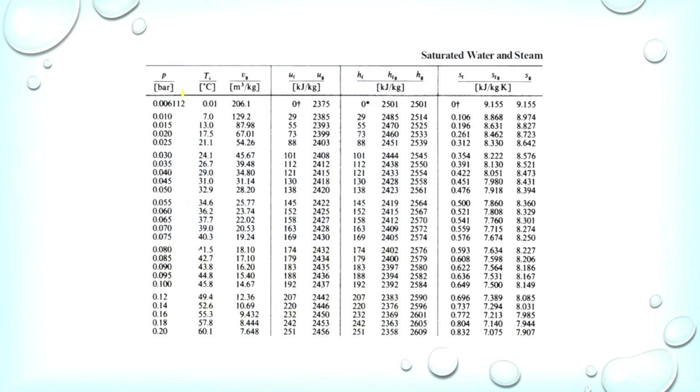In this one it is slightly different, but it's from the same table also. I will provide you with this table. These are called the saturation pressure. As you can take note, whenever the pressure changes, the boiling temperature or the saturation temperature also will change. This is called specific volume, dry saturated. This is internal energy of saturated liquid, internal energy of dry saturated, enthalpy of saturated liquid. This is mixture. Now here you don't have ufg. Here you can see there is hfg.